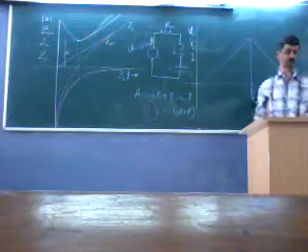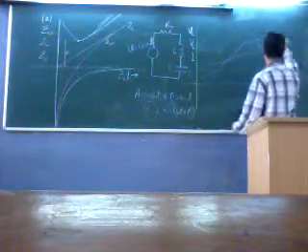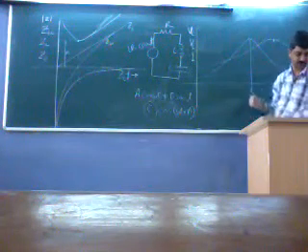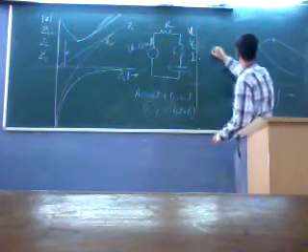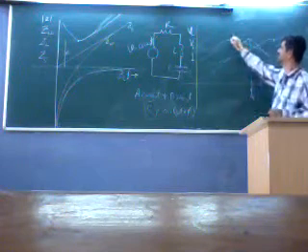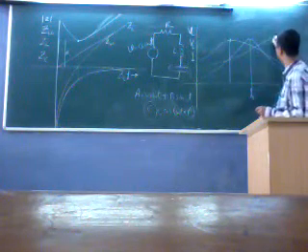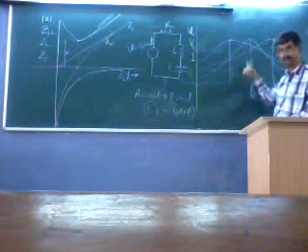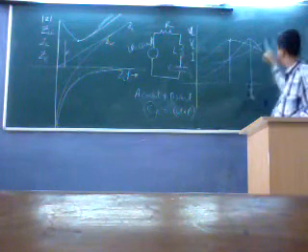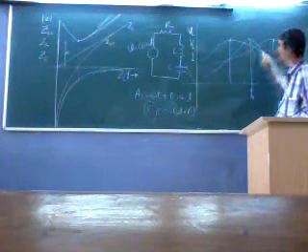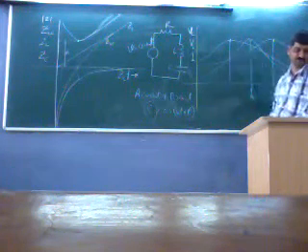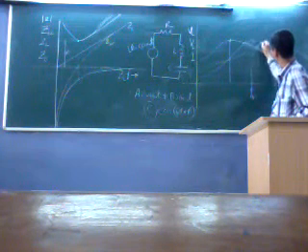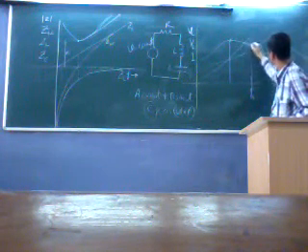And we find that the voltage across the inductor will be like this. It gets a peak somewhere here. Voltage across the capacitor gets a peak somewhere here, like this. It is the frequency at which the amplitude of VC has its maximum value, the amplitude of VL has its maximum value, and I has its maximum value. And at this, both are equal. At resonance, both must be equal.